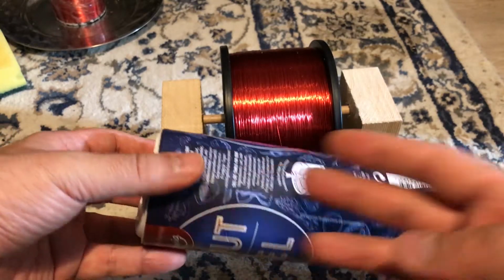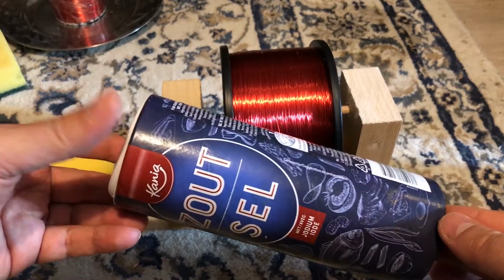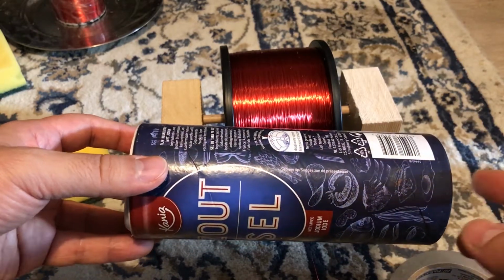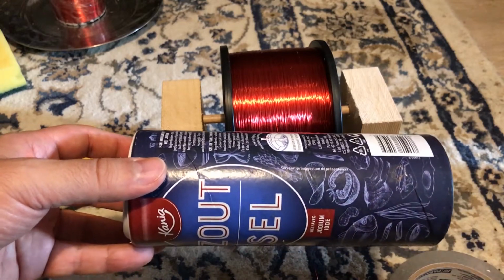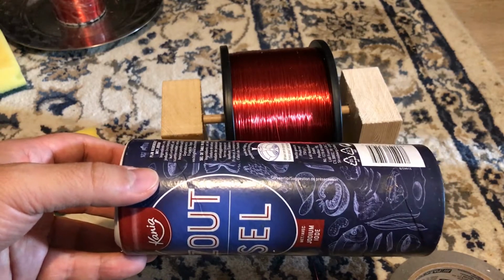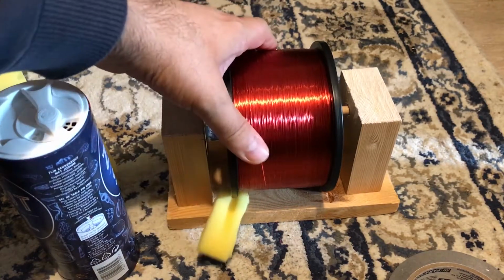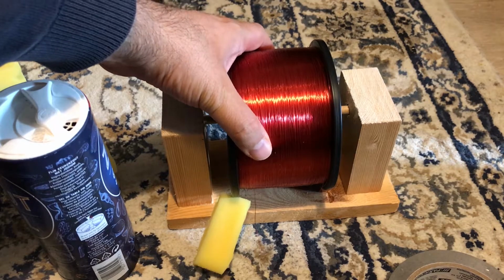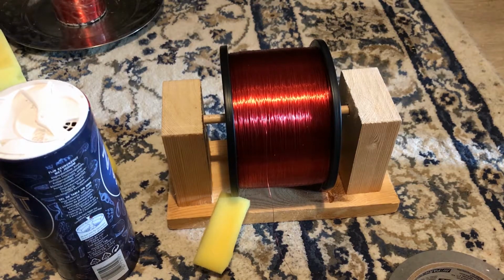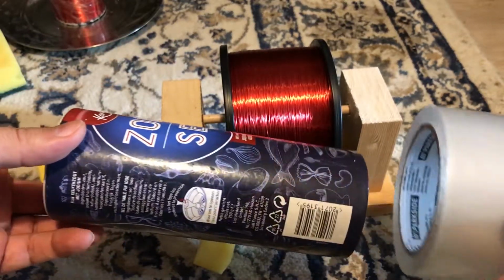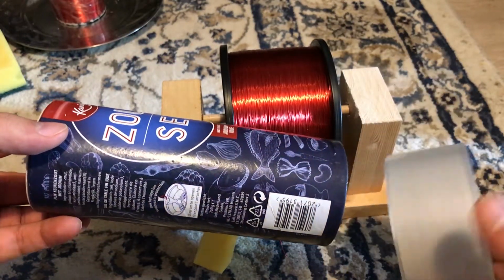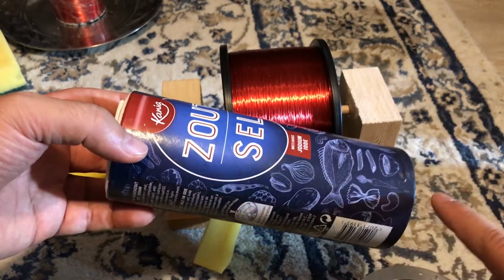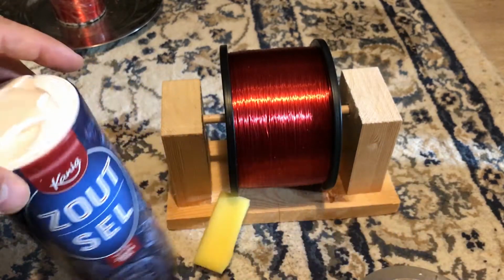Now in my case, I finished the coil and I realized that I didn't count the number of turns. So in order to count the number of turns, I took a high resolution image, and on the computer I counted the number of turns, and it turns out to be approximately 740 turns. The wire that I use has 0.23 millimeter diameter. It's AWG 32. After I made the coil, I put a few layers of packaging tape on it. Packaging tape has excellent insulation properties, so hopefully it prevents damaging the secondary coil.